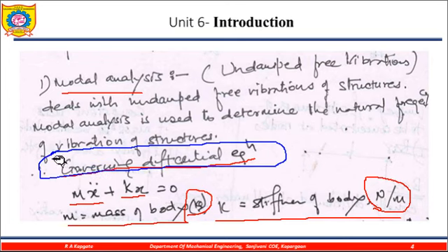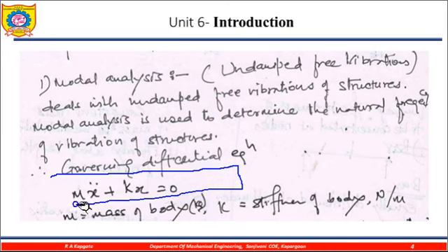You will later understand the importance of this. Now you need to know first of all what the governing differential equation is: m into acceleration, that is d²x/dt², plus k into x is equal to 0. So this is the governing differential equation for modal analysis.